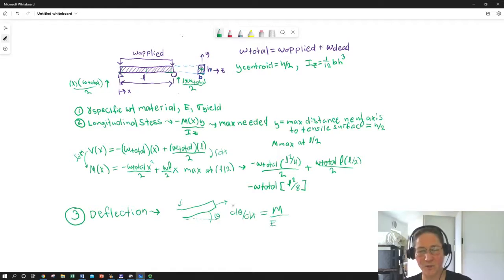So this isn't a max moment unless we're at a max rate of change of deflection, divided by the modulus, divided by, this will be Iz. So here's another case where a bigger moment of inertia is our friend. It's our friend against longitudinal stress, and it's our friend against deflection. So if we want to get actual deflection anywhere along the beam, and this is little v, so this isn't internal shear force, this is deflection in length units, we're going to end up integrating.